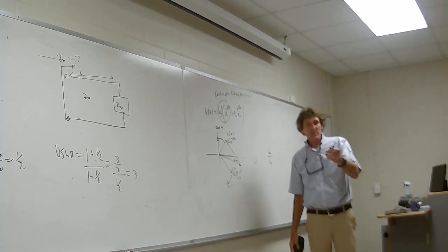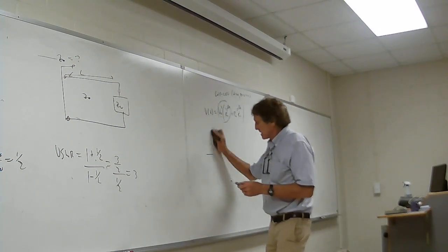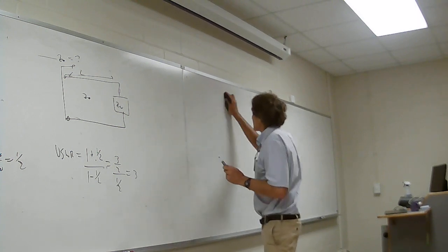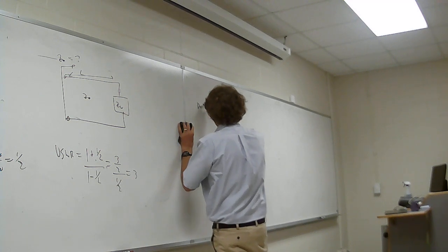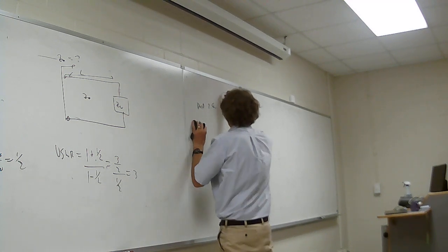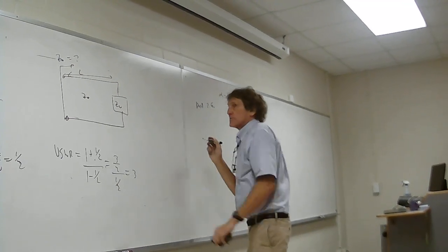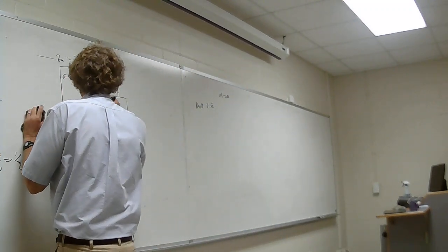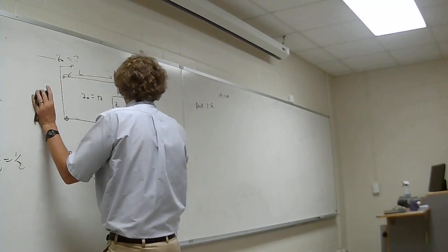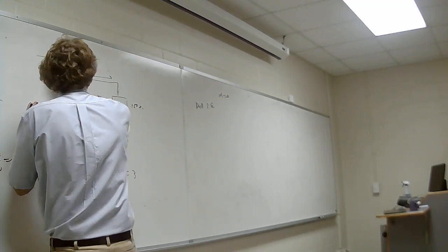Now, let's keep going to the next problem that's related to this. Is it drill 2.8? Yeah. Okay. Suppose the terminated T line for drill 2.7 is lossless. Find the impedance for a length of line equal to lambda over 8. So now what he's saying is, for Z naught equal to 50 ohms and the load equal to 150, he wants to know what the input impedance is for different line lengths.